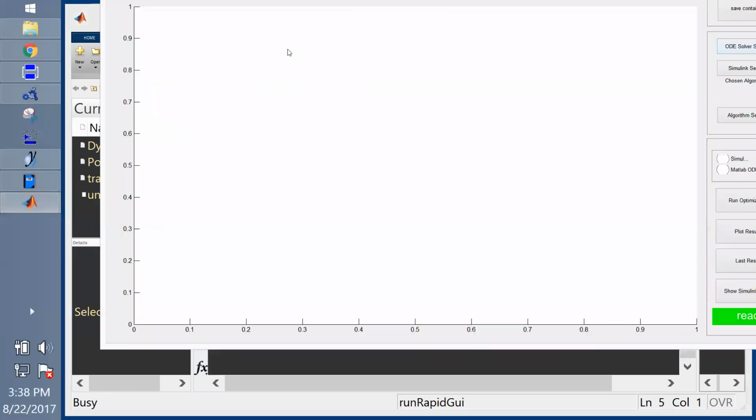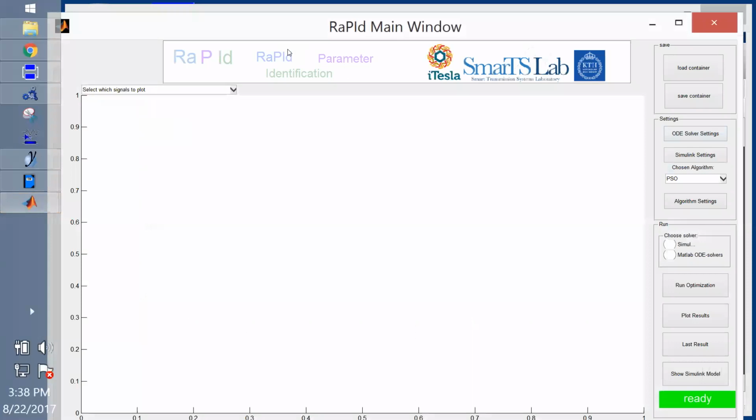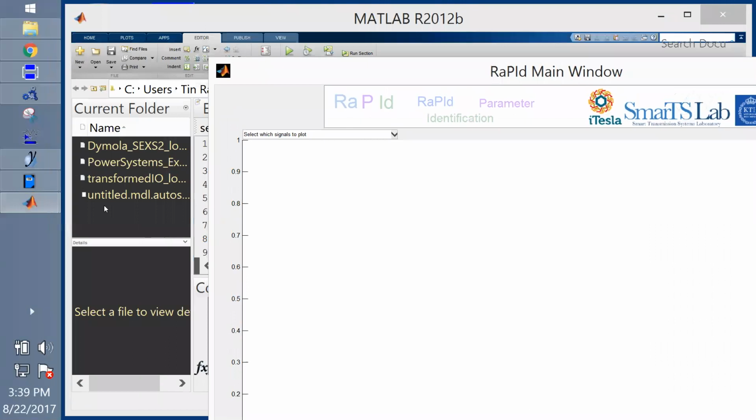The way it works is that you have your Modelica model, and then you want to simulate it somewhere else. You can simulate it in other Modelica tools, as I have just shown you. But MATLAB doesn't use Modelica, right? So there is this library called the FMI toolbox for MATLAB Simulink. That allows you to use the same Modelica model exported in the FMI standard inside of MATLAB Simulink, and you can use it only in MATLAB, just by scripting, or in MATLAB Simulink graphically.